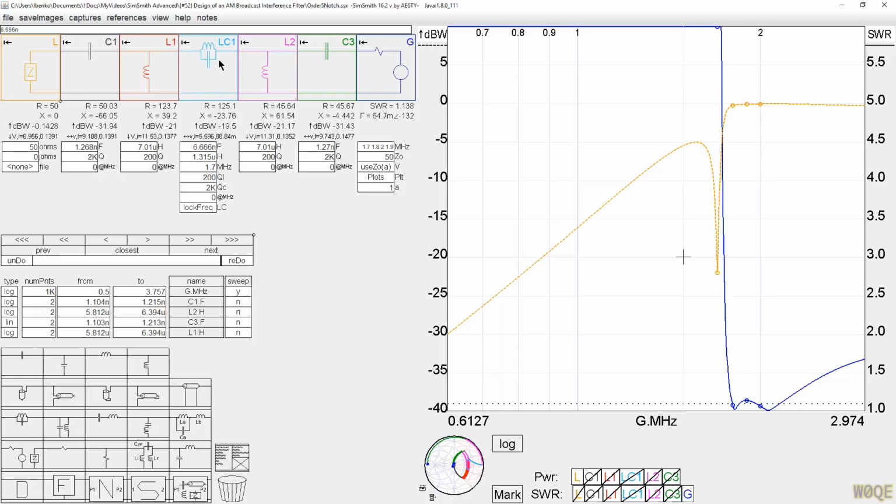This does not look like a capacitor. Before, when we had a capacitor here, it was a capacitor only. And by putting this inductor in here and making this resonant, moving 100 kilohertz away, this is not a capacitor yet. It's capacitive, but it's not enough of a capacitor that these components can be the same values as they were before. If we had looked for a notch down here, we'd have been able to just put a notch in here and hardly adjust these at all. But being able to play like this in SimSmith is an incredibly powerful tool. And there's no way in the world I could have put the parameters into a program like LC and gotten a filter like this out of LC.